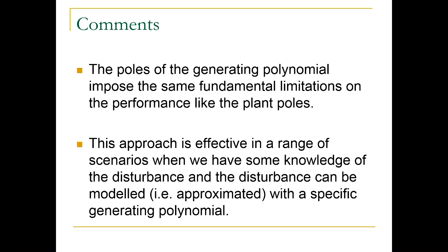So there will be all these trade-offs that you need to bear in mind. This is very effective when we know just something about the disturbance. We don't need to measure the disturbance exactly. When I model disturbances, I just said they are constant. I didn't expect you to tell me the amplitude or the value of the disturbance. I'm just saying this class of disturbances will be possible to reject with this structure of the controller. I just need to know that the disturbance belongs to this class. That's a very cool general result. We do not measure disturbances, but we reject them.